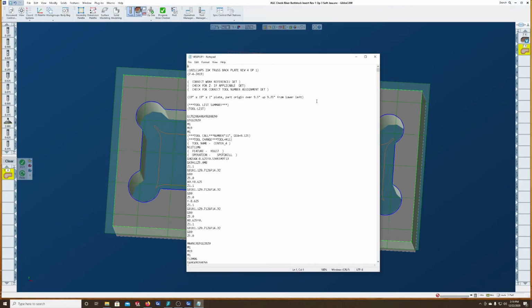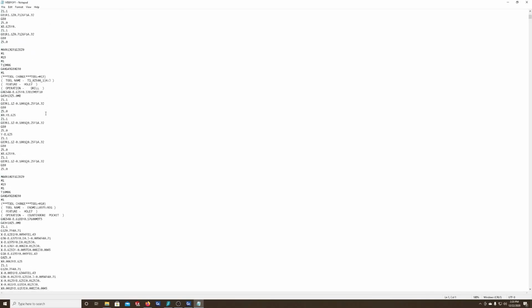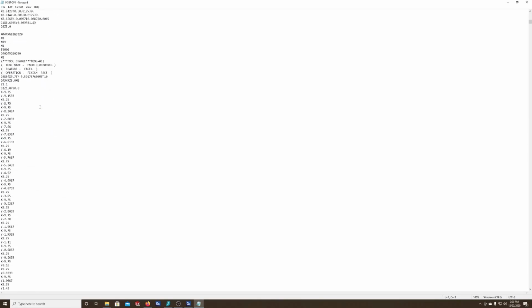And this is an example of G code for that 14.5-inch IDK part. And you can see basically it's a bunch of different types of code that set parameters in the machine. And then it contains X, Y, and Z coordinates that tell that end mill how to move through the part, along with what type of RPM. M8 turns on cutting coolant, which helps keep the materials cool, helps prevent buildup on the end mill, and also washes away chips. And the CNC machine will then process through all of these changing tools to machine that part.